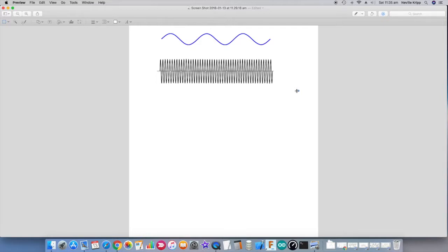So we've got an audio signal here, which is down around the 100 to 10k hertz, and we need to somehow get that information applied to the carrier signal. And what we actually do is simply control the amplitude of that carrier wave using the audio signal, which is effectively just adding the amplitude of the signals together.